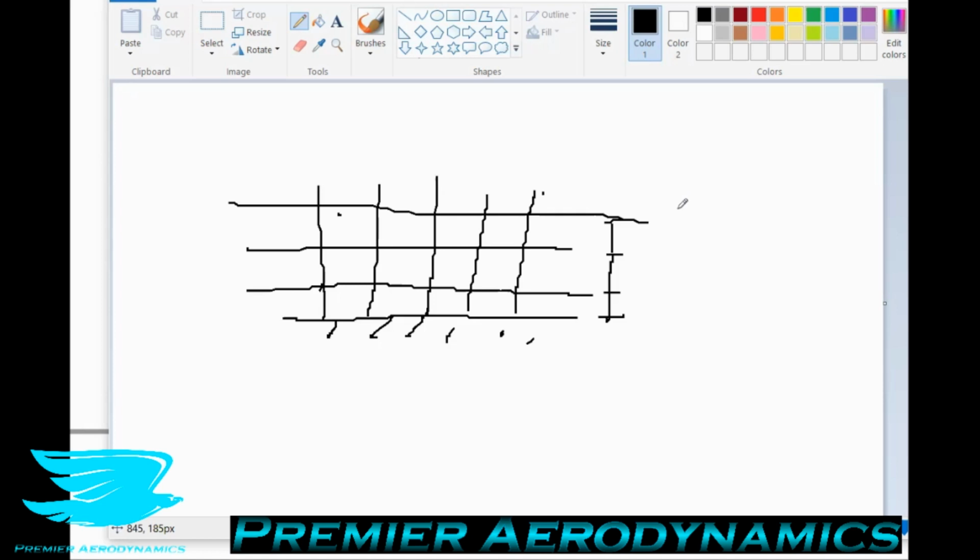That's DES. DDES and IDDES stand for delayed detached eddy simulation and improved delayed detached eddy simulation. It's very heavily in semantics, but effectively what this does is it staggers, like you have to go further away from the wall for LES to kick in. And there are these things called shielding, which is when certain properties are triggered, LES will not trigger and you still stay in the RANS.